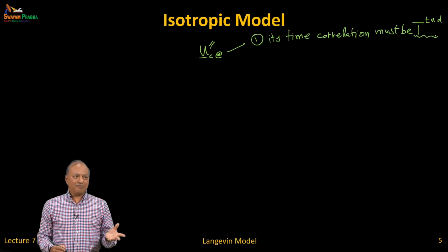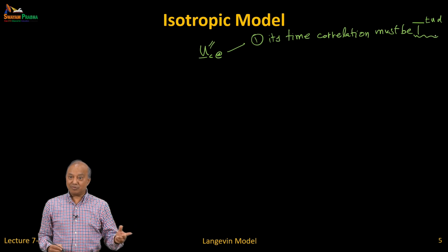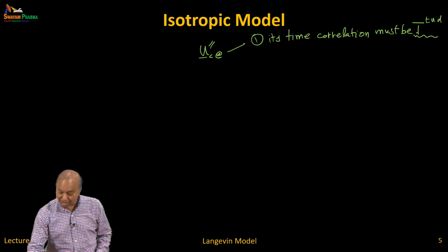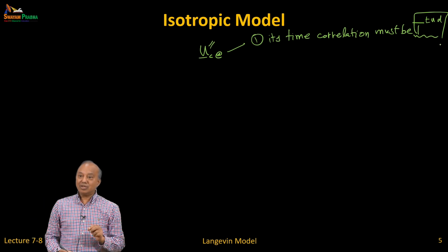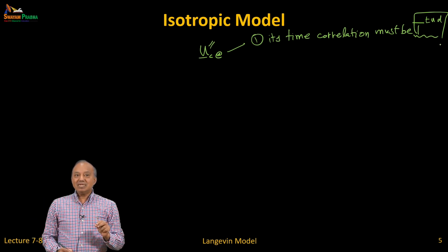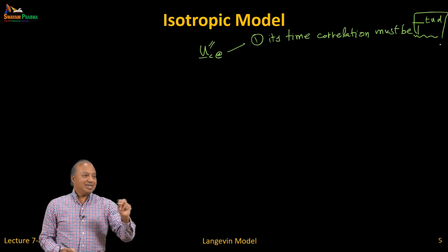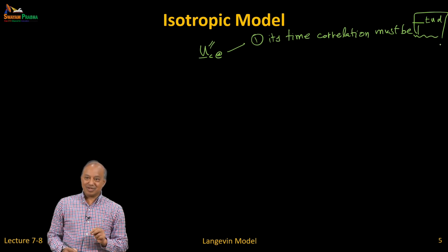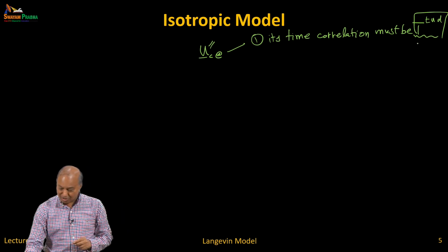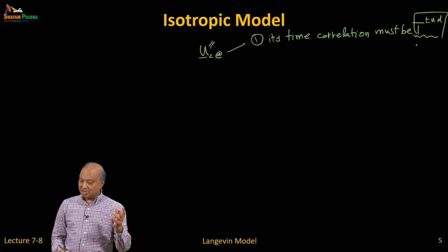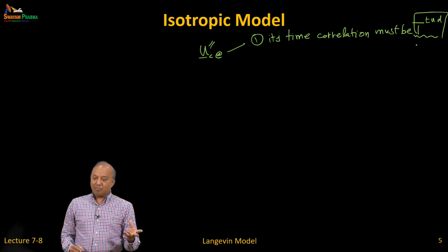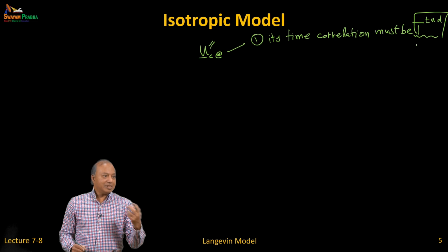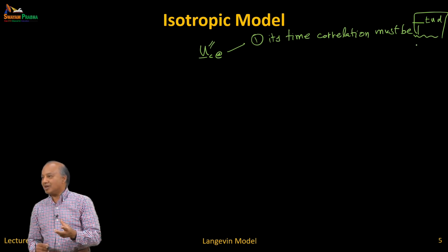When you do DNS and track particles, you can ask how much it remembers the velocity fluctuations. You can use DNS to calculate this. This depends on how long a particle is going to sit inside an eddy. Till it's in an eddy, it will have a certain velocity fluctuation.